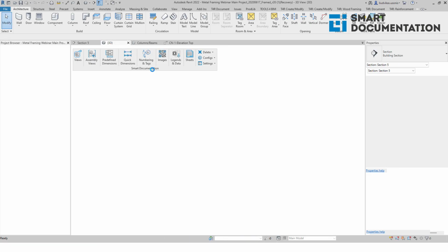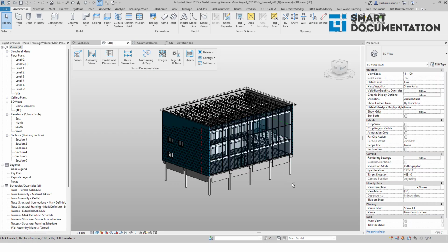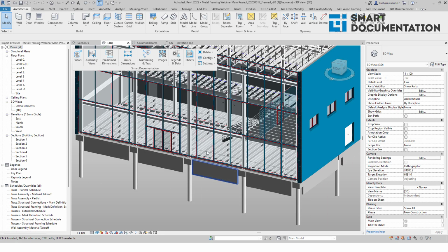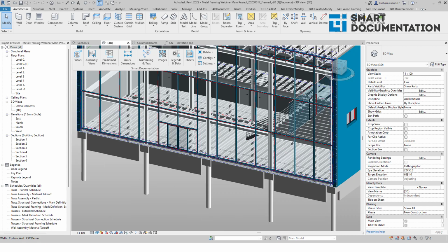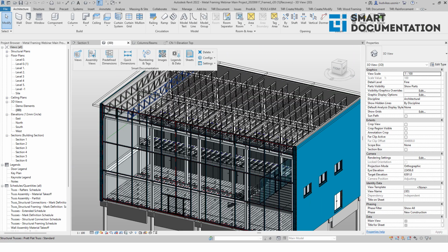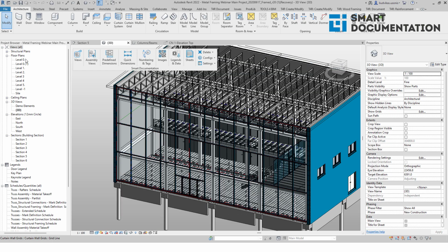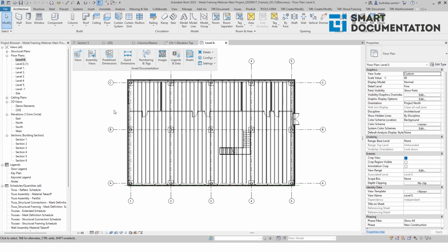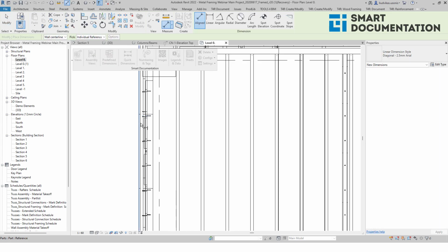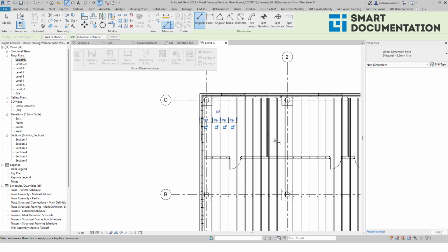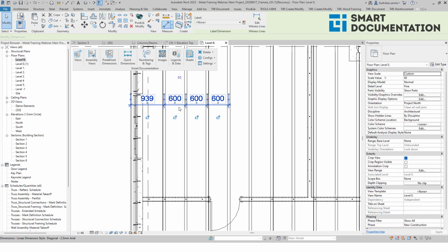Alright, next sample. I'm gonna show this sample, and here I have this Revit model where I have many steel joists at this level, and at the top I have trusses. Now I want to measure these elements. So what I do typically, I select dimensioning, and I want to dimension center, right, from wall to the joist. I need to press tab, I need to catch the middle of this joist, and I'm gonna do that for this floor plan, for another, and so on. And that will take lots of time to do.